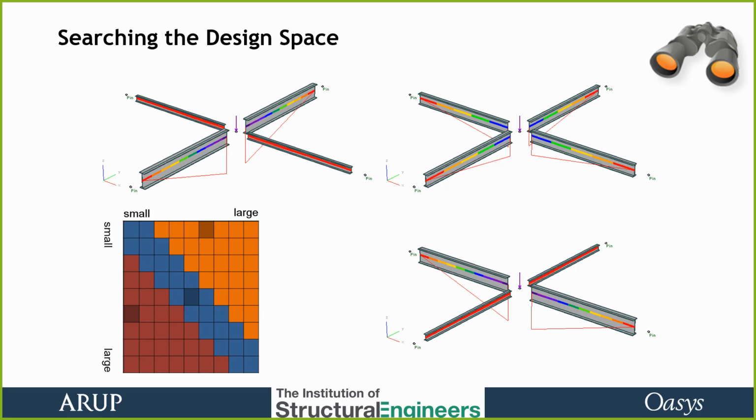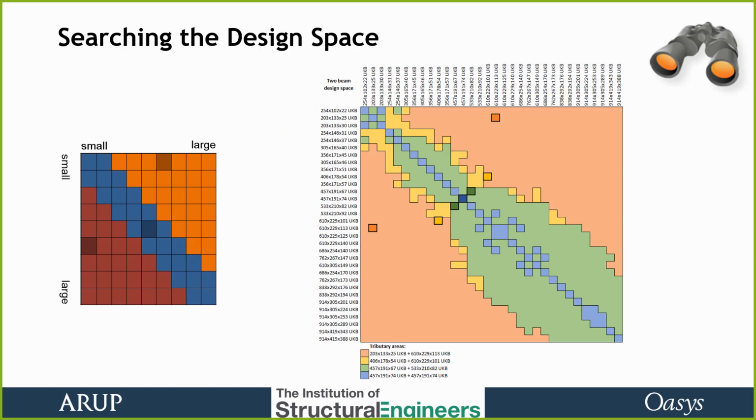and then I wrote a little script which actually ran through all the options. And so I discovered it was a lot more complicated than I was expecting. Now, if we see the chart here, the blue spots are choices of beam sections which do end up with the completely symmetrical section, as expected. The orange, peach, go to these orange results here, very asymmetric, but to my surprise, there's also these nearly symmetrical sections, which I didn't expect, but